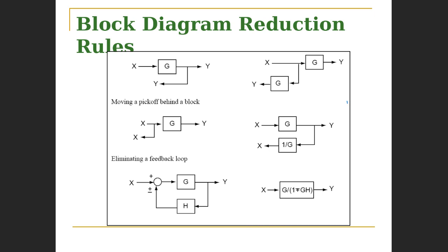Go ahead, please. What I was thinking about, if you remove the plus from the bottom and say then X minus H times G equal Y, would that be correct? All right, so you started the process. We're trying to simplify the block. So what signal is going into G? Plus and minus, so we're crossing out the plus on the lower side. So it's negative feedback.